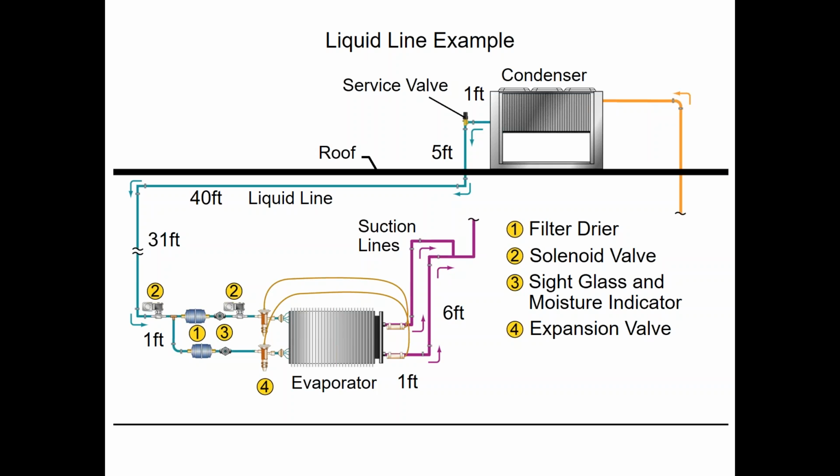You can't have traps everywhere, like lift station traps. The only true trap, like a J or P trap, is in a double suction riser or a double discharge riser. Outside of that, you shouldn't have any other traps in the unit, with the exception of the inverted trap at condensers, but inverted traps don't store oil.